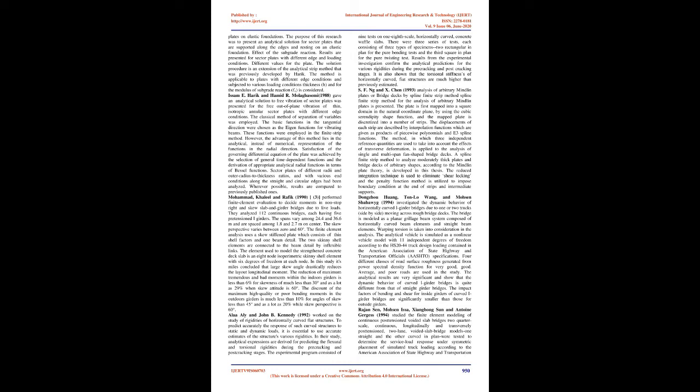However, the advantage of this method lies in the analytical, instead of numerical, representation of the functions in the radial direction. Satisfaction of the governing differential equation of the plate was achieved by the selection of general time-dependent functions and the derivation of appropriate analytical radial functions in terms of Bessel functions. Sector plates of different radii and outer radius to thickness ratios, and with various end conditions along the straight and circular edges, had been analyzed. Wherever possible, results are compared to previously published ones.